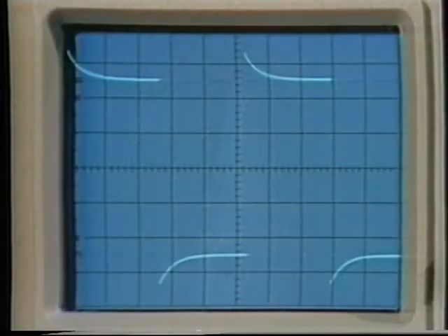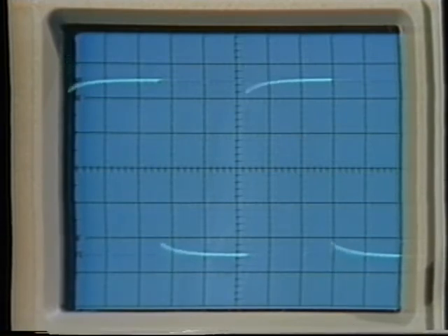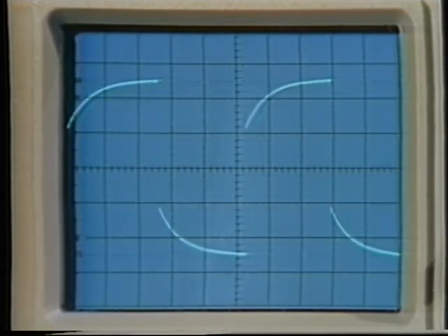If we don't compensate the probe, our attenuation will change with frequency. If the probe is undercompensated, there will be too much gain at high frequency. If the probe is overcompensated, there will be too little gain. Either way, you're left with a measurement that may or may not be accurate. As we go up in frequency, the capacitive input characteristics of the probe change in other ways that can be important when we select which probe to use.